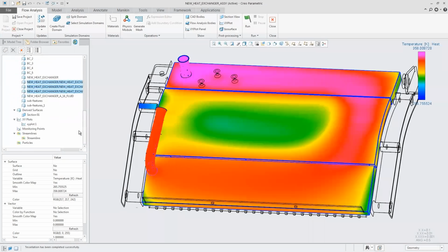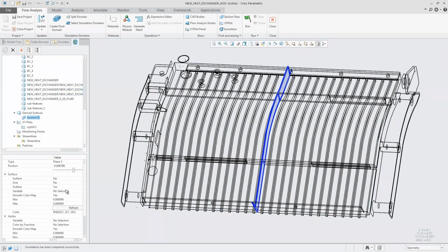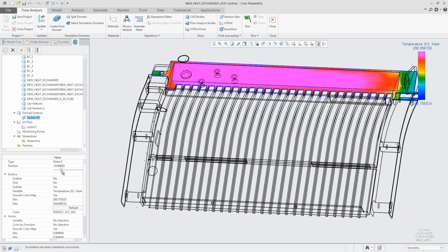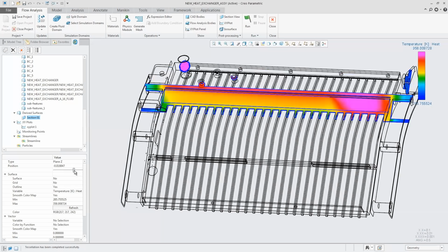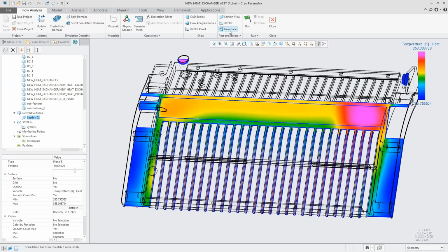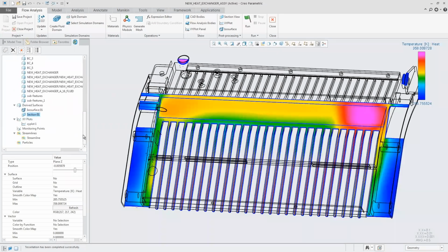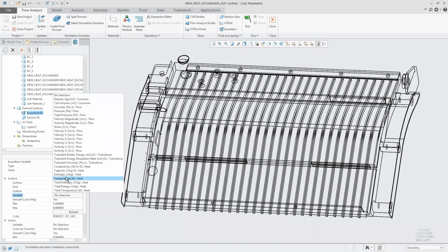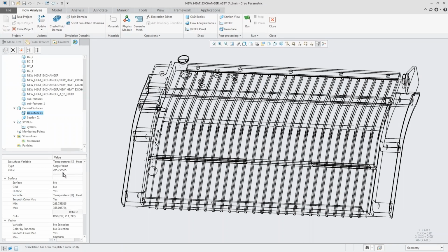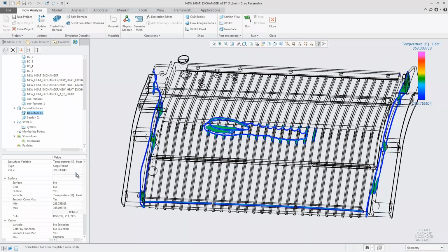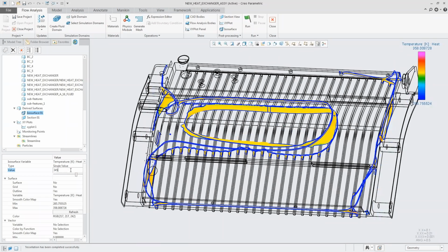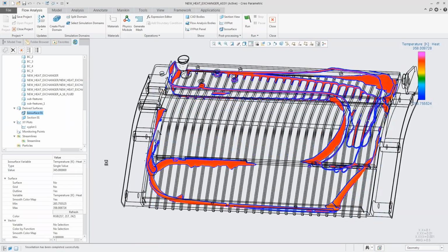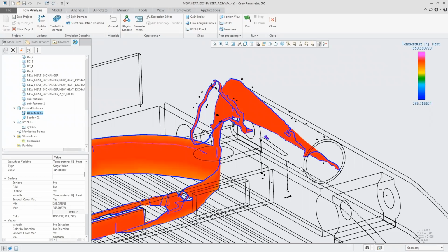One of the useful tools we have of this as well is the ability to take section views of the results. So say we wanted to look at the temperature values inside of the model. You can move that to the X plane, check it out in the Y, see what it looks like in the Z, move that around. And then another powerful tool that we have at our disposal is the ability to actually search for specific values throughout the simulation. So first we have a slider bar that we can move from a minimum to a maximum. So we can check out where those values are. So check out for different things. Also, if you wanted to see at a particular value, say you wanted to see at 345 degrees Kelvin, you could just type that in and I could check that right up there on the model itself. So very easy to go through, check out some of the results for the study.